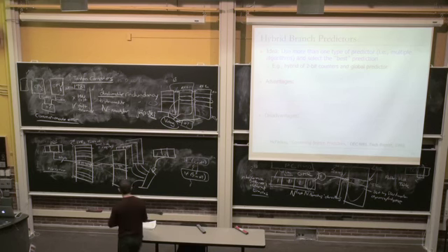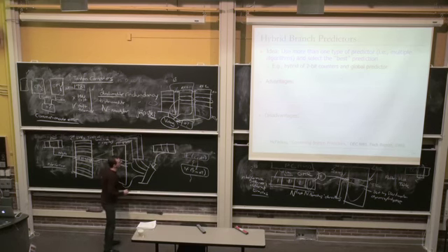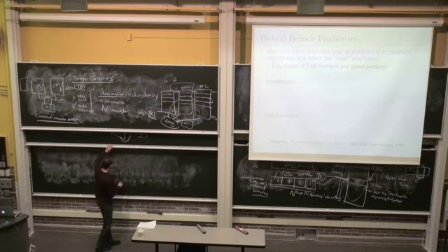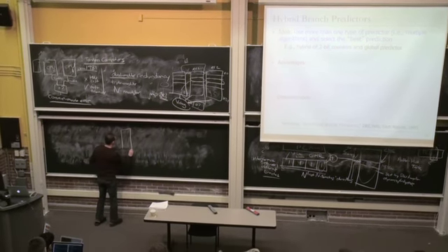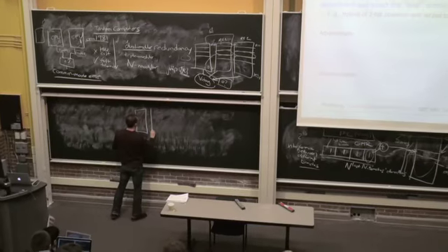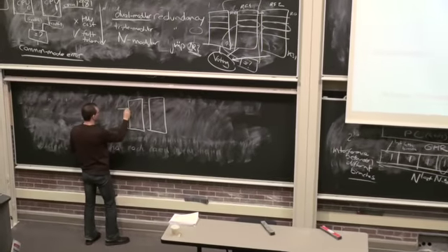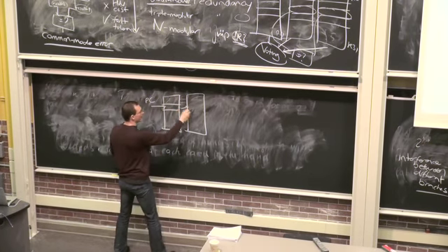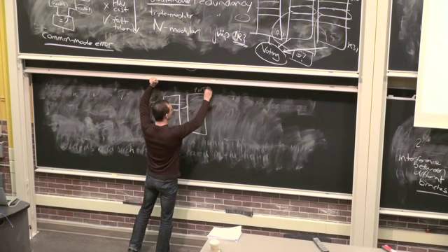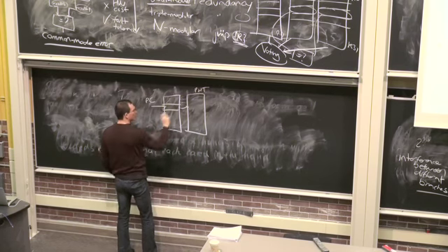So, well, I'll give you a picture of this, but so what you can do is you can have one predictor like this, your program counter, and history for that program counter, and the pattern history table. Where did the branch go for that program counter?